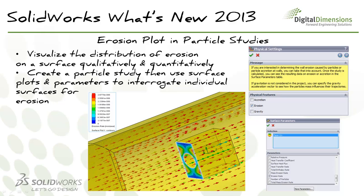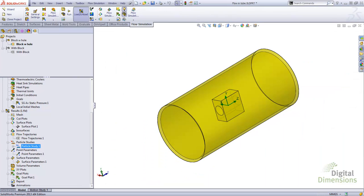The next ability to point out for Flow Simulation 2013 is the ability to add erosion plots in the form of surface plots as well as surface parameters in your results. When you're exploring your flow structures with two phases, whether that be water and gravel, or any liquid and solid, you can display these erosion rate surface plots or determine quantitatively with surface parameters what these values are with any surface involved in the flow project.